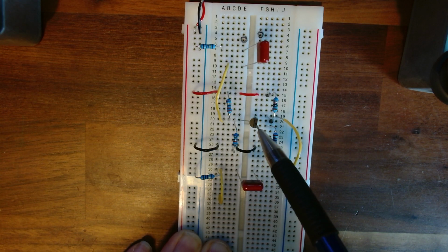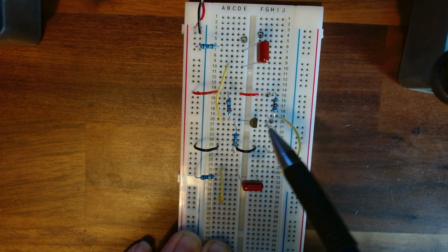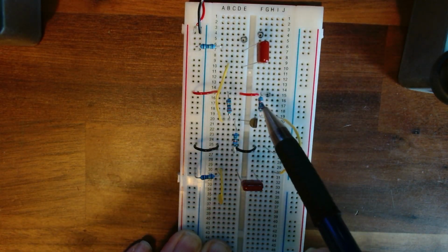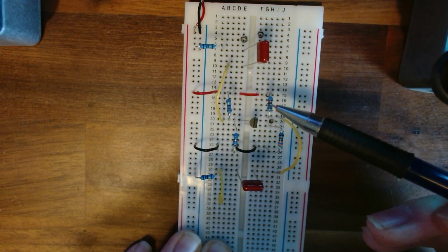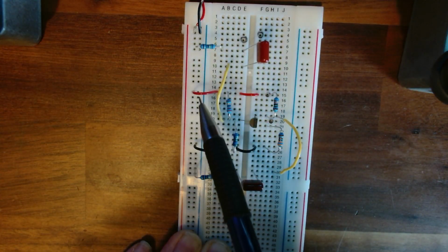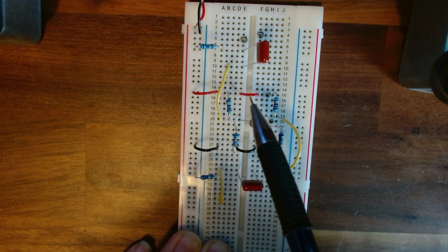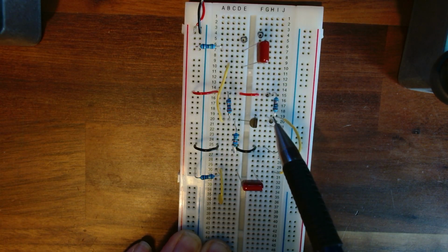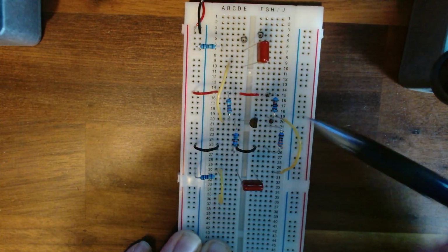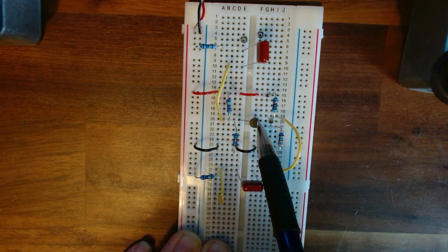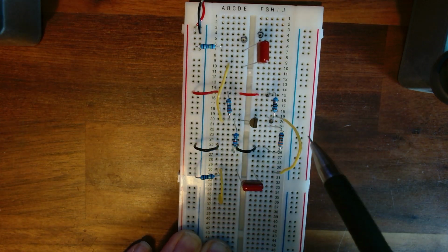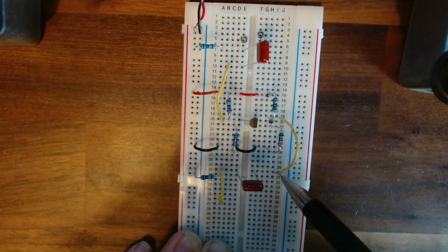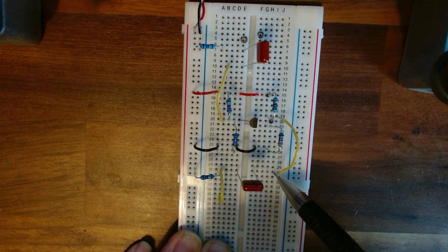So that brings us to pin 2 of the transistor, the input, the base. And if we follow this through, we've got one leg going out to pin 19 and one leg going out to pin 21. So this one here is our 10k, and I've jumpered across on the same line over the trench on pin 15, and it's going from the power to line 19 to join our collector. And we're also going to take our output line from that same point, pin 19, over here somewhere to pin 30, just out the way.